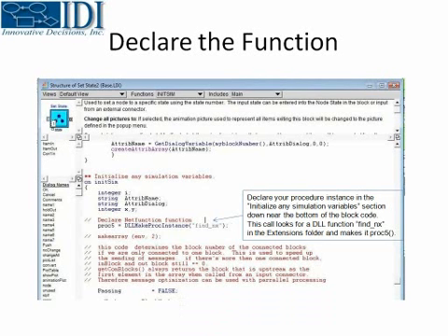So I'm going to declare this function and use the command DLL make procedure instance, and then you see the name there in parentheses. The name in parentheses is the actual name of the function that's in the DLL that's stored in that extensions library. So that will search through the DLLs that are in your extensions. If it finds NX, then it will not generate an error, and it will initiate that to procedure 5.